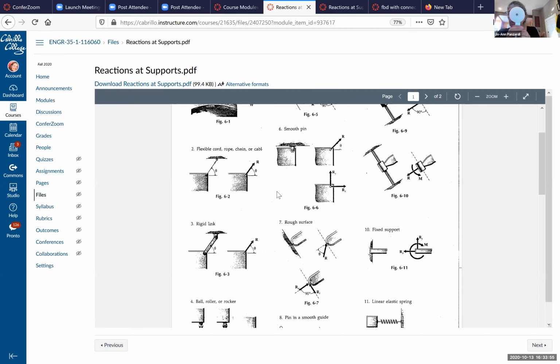What kind of motion can these 2 objects have relative to each other? They can have a rotational motion. Okay, they could have a rotational motion about z, right? We're going to assume on all these 2D problems, this is my x and this is my y. So it could have a rotational motion about z.